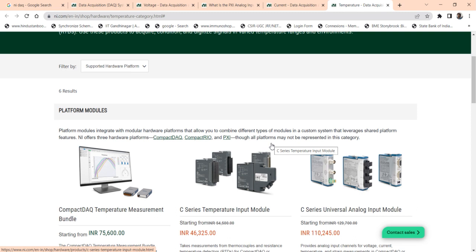Arduino can only work between 0 and 5 volts. So you cannot measure negative data like -2 or -3 millivolts or volts. And you also cannot measure 10 millivolt, 10 volt, 20 volt, 30 volt, or 60 volt data. So there is only some kind of data acquisition you can do using the Arduino.